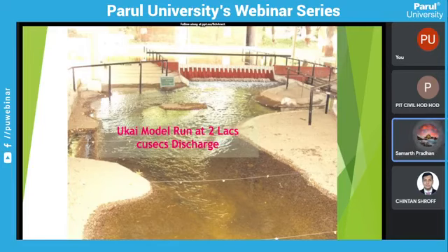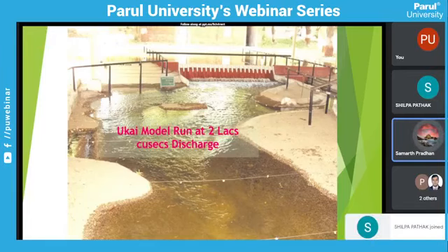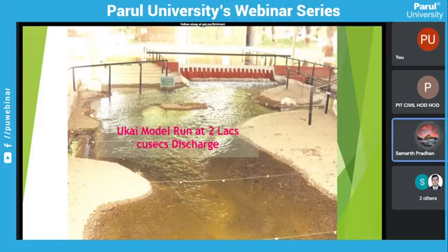See here, the meandering is there. Whatever water is coming through these gates, due to this turning the velocity is very high, so it is eroding this bed. This natural bed is totally eroded. For that, they suggested protection work. So the earlier protection work was tested. See here, the earlier protection work is also there.